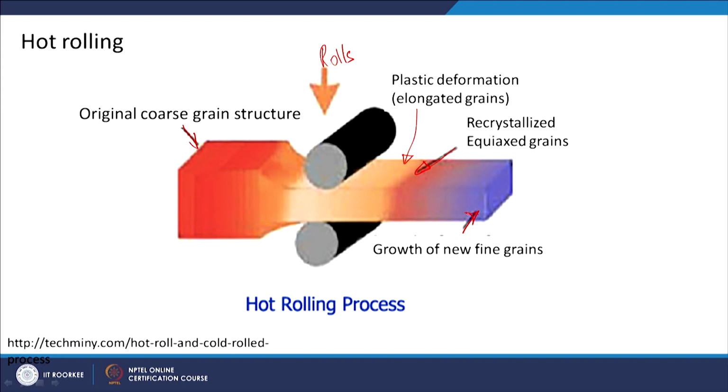Basically, the idea is that you have to refine the microstructure and break the coarse grain structure. There will be multiple stages. In the first stage you would like to break the dendritic structure, then you do some annealing, you have some coarse grain structure, then you go for fine grain structure and so on, and then you will go for cold rolling processes later on.